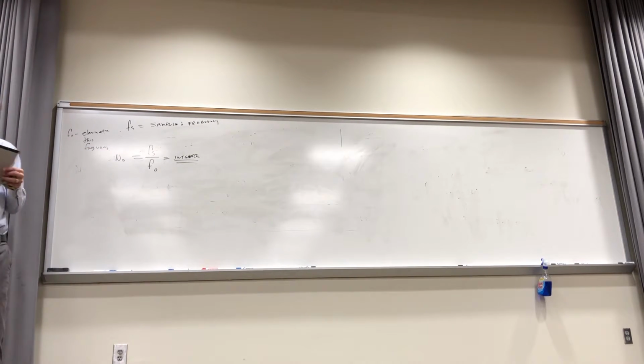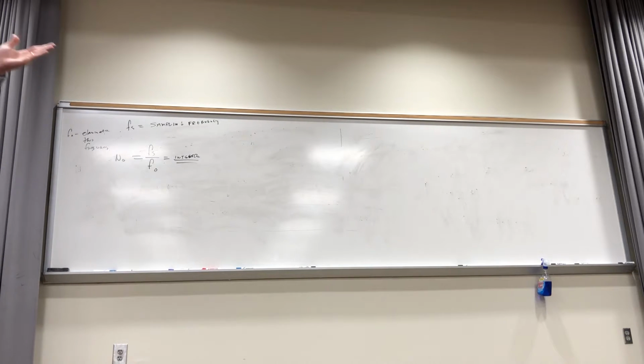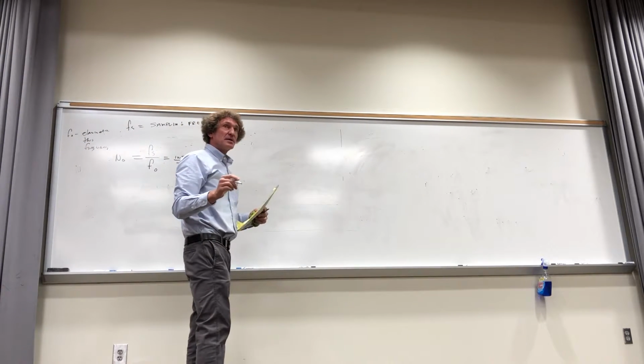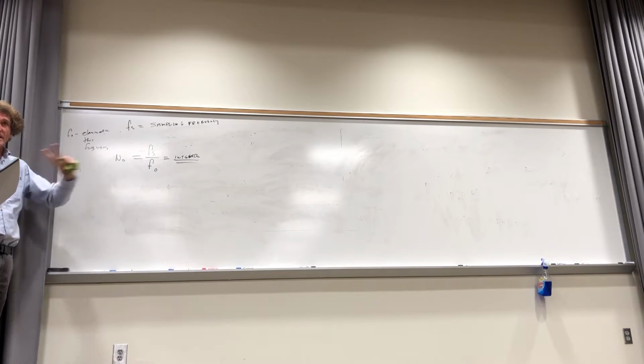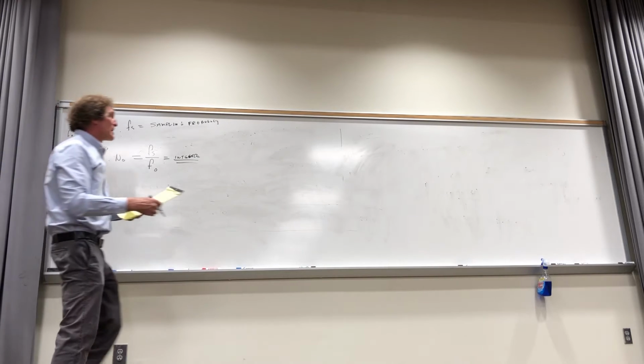We want to eliminate that frequency, just like we wanted to eliminate 60 hertz before, all right? That's the frequency, but this will get rid of the harmonics too. It'll get rid of 60, and it should get rid of 120 and 180 and all the way up the line, one filter. Now, when we look at this, the way they're going to say to do it is, if this is an integer, and if it's not, you can't do it this way. Then you need to cascade it like I did. If it is an integer, then you can have this equation.